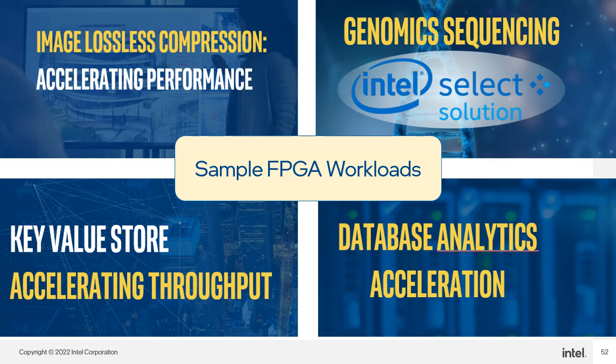Genomic sequencing is similar to compression. It also involves comparing present and past values in large volumes, and the FPGA performs these algorithms really well. Key value store is basically hashing, and it is used for database. You find such algorithms in bitcoins. It takes advantage of the memory structure of FPGAs. Thus, you are able to pull a lot of values out at a time and compare against a set of other values all at once in very few clock cycles. Database analytics is also similar to key value store. You find that all of these algorithms take advantage of the custom memory structure FPGAs can build for you.